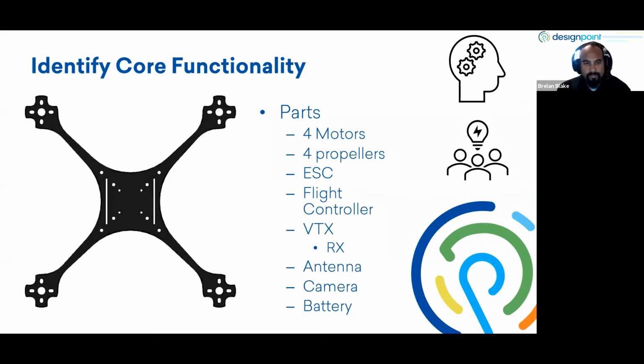With our electronics, if you can see in our image to the left, it's an X design of our quadcopter. We incorporated some different bolting pattern features, which we'll go over a little bit later. But that will incorporate our electronic stack. Our stack is our ESCs, flight controllers, and all of our electronics stacked on top of each other. They're bolted together. In the middle, we use our ESCs, which stand for electronic speed control.